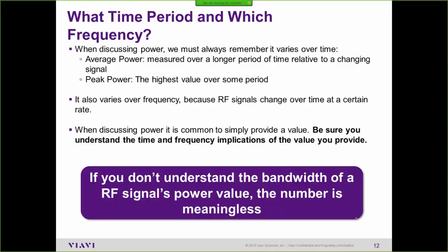Well, I would assume that'd be neg 90 dBm. That number doesn't mean anything when you say just RSSI because it doesn't have a bandwidth tag to it. Now, you can probably assume when somebody says RSSI, they're talking about a channel bandwidth, and if you know that channel bandwidth, the number starts to have some meaning.